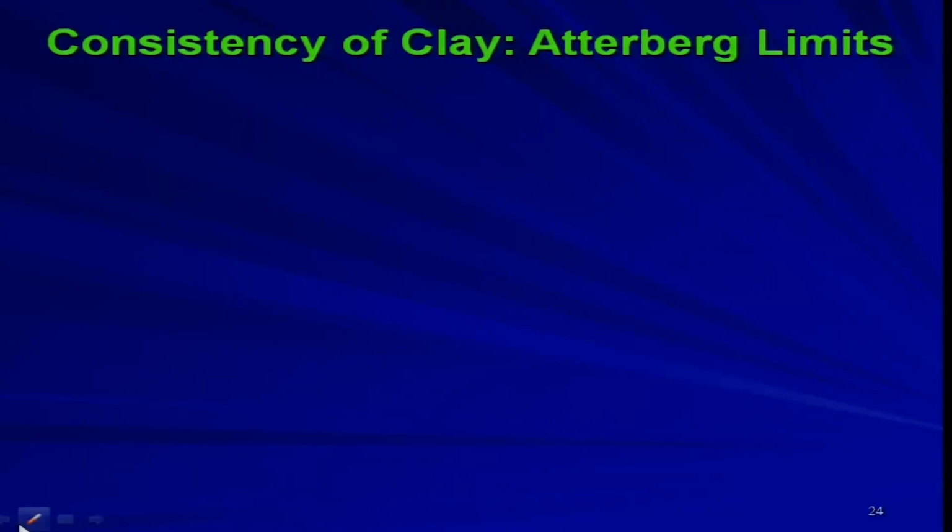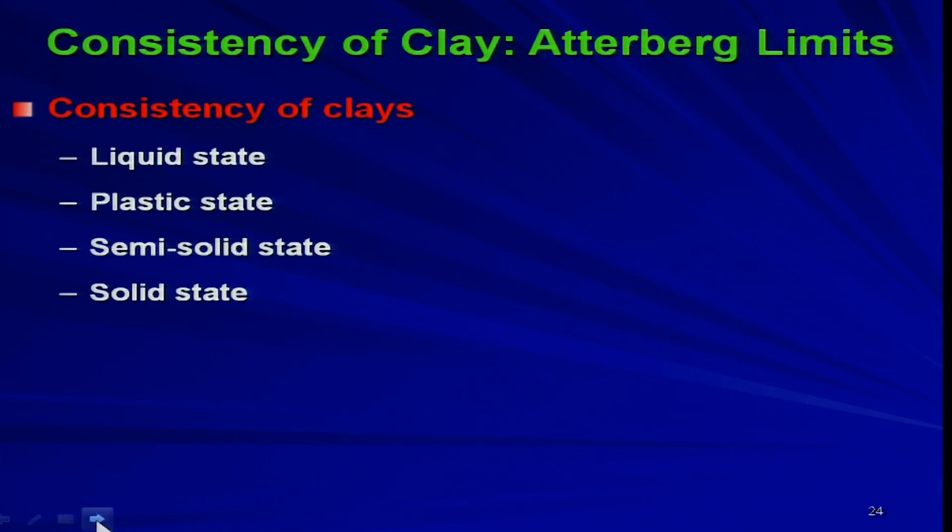Okay, welcome back to the course Geology and Soil Mechanics. In the last class we have seen the sieve analysis, grain size distribution and hydrometer analysis. Then we just started the consistency of clay with Atterberg limits. Basically, the consistency of clays is categorized by 4 states. First one is the liquid state, then plastic state, then semi solid state and solid state.